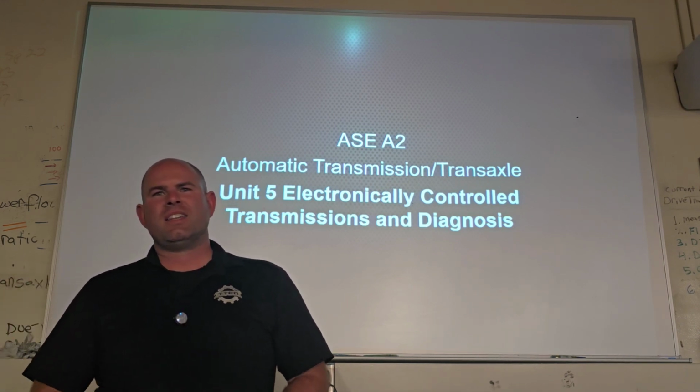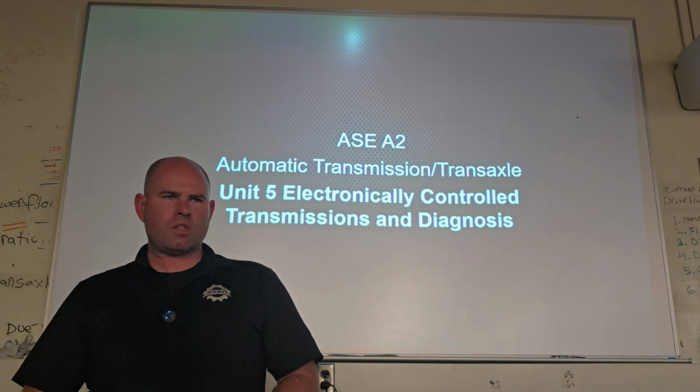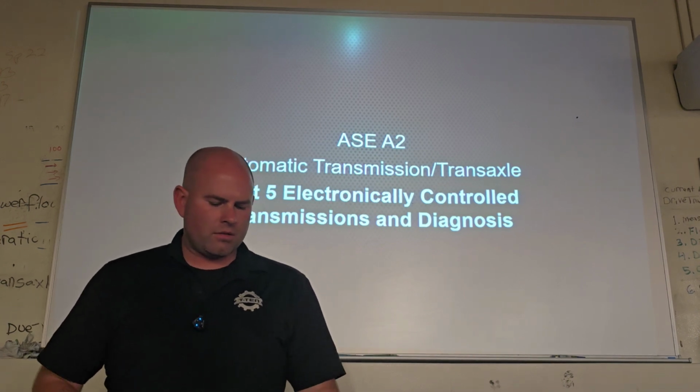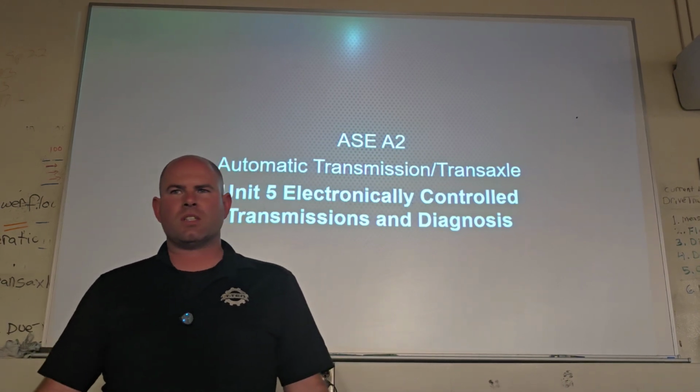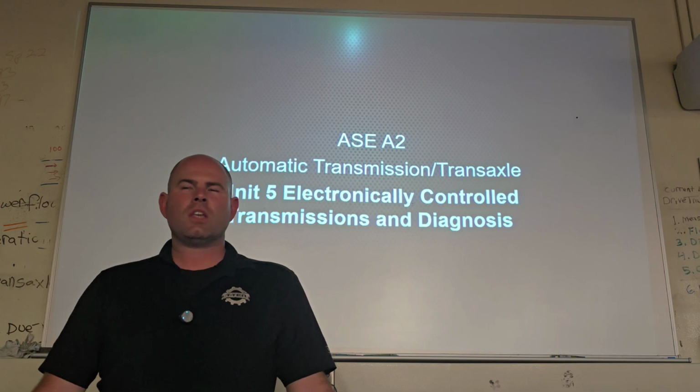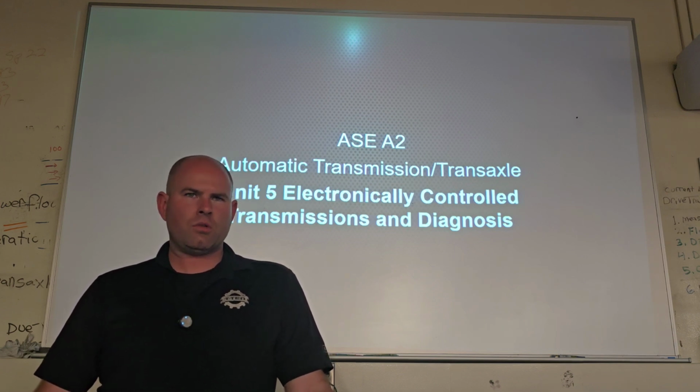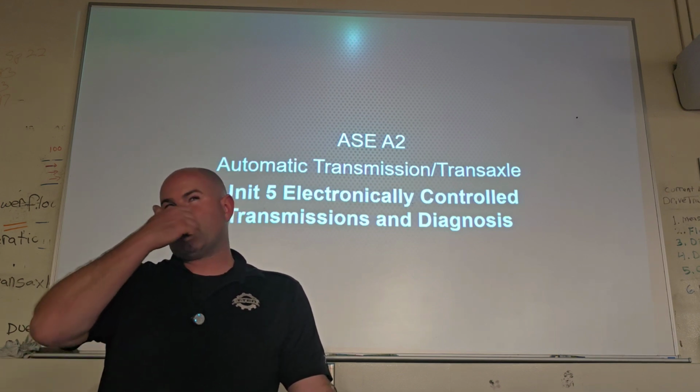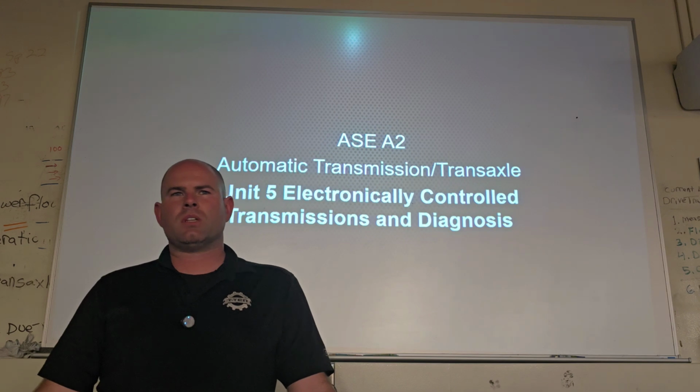Line pressure testing. Yeah, a lot of pressure testing and road testing. The electronically controlled transmission, to me, is actually easier to diagnose. You can get more information right from the scan tool. And I'm going to say probably more than 9 out of 10 times, if you have a problem, it's mostly going to be DTC based.